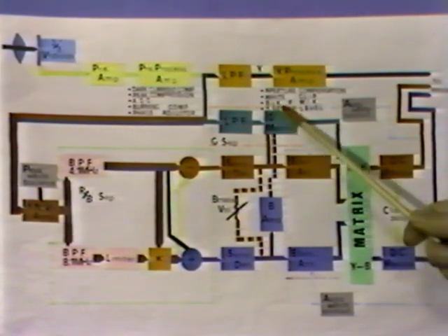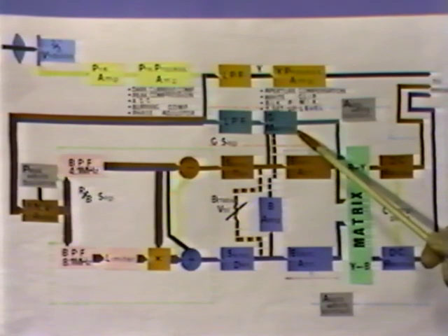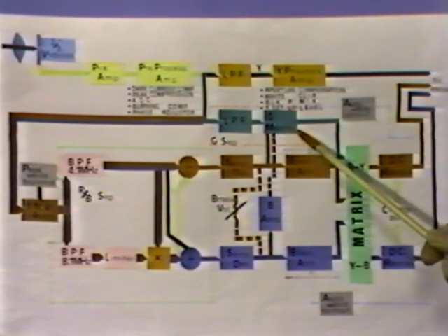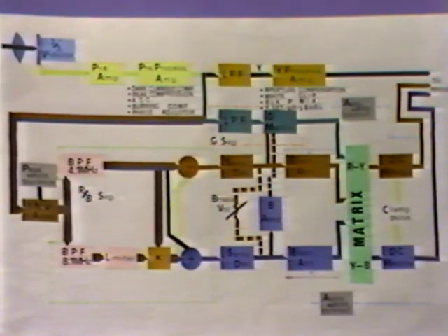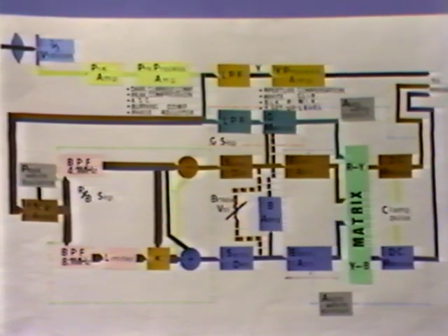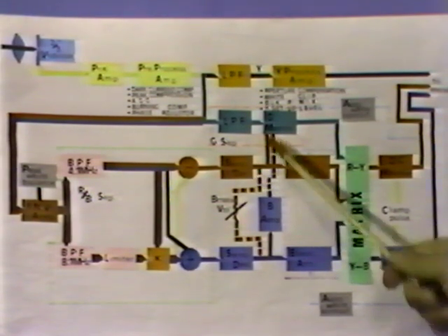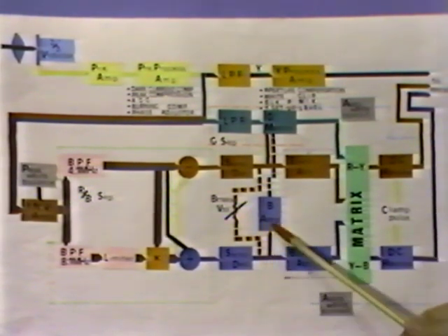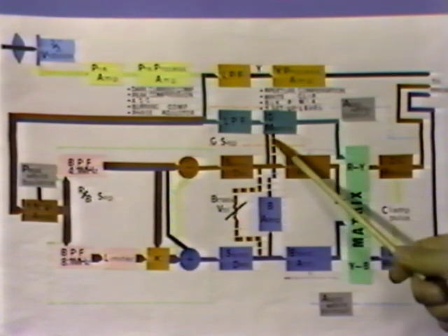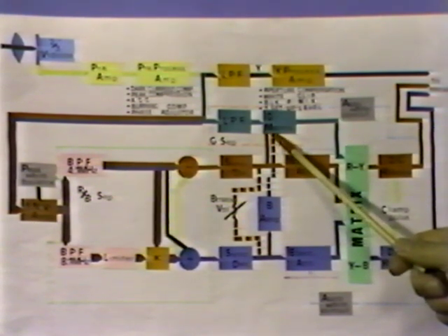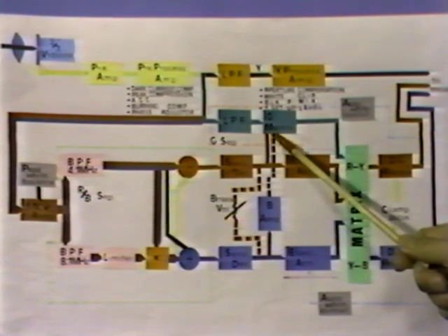Then, the G matrix works to cancel the unnecessary B and R components of the low-pass filter output and to produce the pure G signal. This cancellation is done by detecting R and B and feeding the reverse phase R and B signals back to the G matrix.